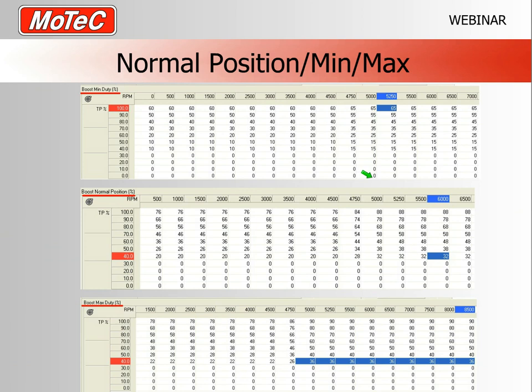So the computer starts with this number here, 88% duty at 5,000, and no matter what the calculation, it will never go below 65 or above 90. Alright, so you are clamping how it works. Now, as I said last time, if you clamp it too tight, you're preventing its ability to respond. So you need to bear that in mind. But initially, this is all about getting this to happen safely.